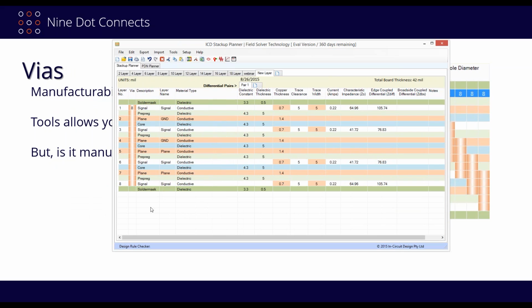And in a similar fashion, whatever's going on layer 8, I may need the assistance of layer 6. And of course, I'll have a through hole, so if I do need to send things through, I'll send them through from layer 1 down to layer 8. So what we're dealing with over here is an example of buried vias. So I'm going to throw a couple of those in here right now.